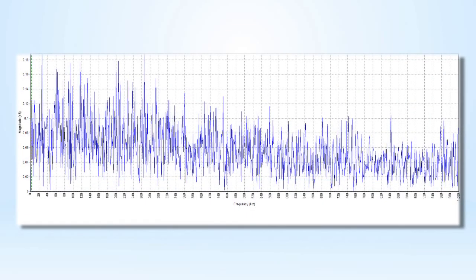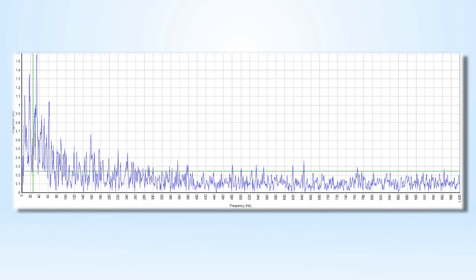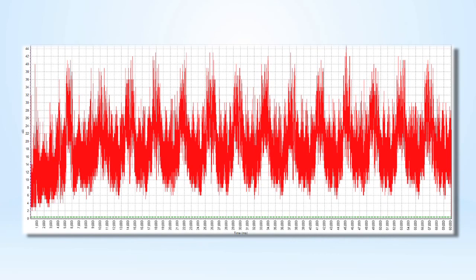AE Lab. AE Lab was created in order to view the full dynamic envelope of an acoustic emissions signal. This analysis is not essential with the Kittiwake Holroyd device, but can yield further information as to the nature of the defect. The minimum speed of rotation for spectral capture is 120 RPM. This mode can be accessed on the MHC Memo Pro by selecting No to Routes and selecting Standard Mode Readings. Capture Spectrum can then be selected, allowing the creation of up to 15 spectrum files.